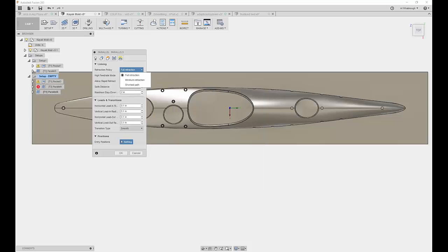If the rapids would be doing dogleg, then we wouldn't be able to simulate it as it's actually running on the machine. So we really want to make sure that what you see in the simulation matches what you get on the machine. So it would be very dangerous to rely on rapid motion for these kinds of moves, because there could be some deviation.